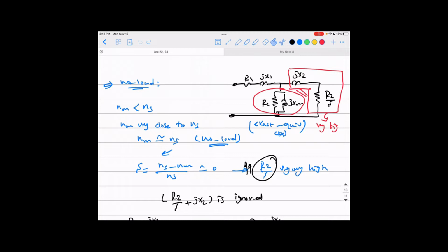That means there is induced voltage in the rotor coming from seeing the stator flux changing in time, and this will not happen if the rotor speed is the same as the magnetic field rotation of the stator, which is the synchronous speed.